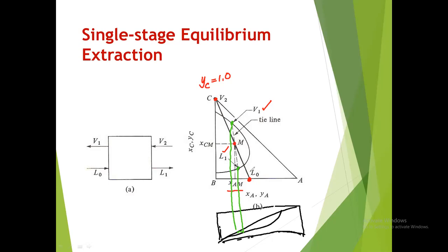On this particular line connected by these two points, you have the bulk phase M taken from the projected concentration XAM to this particular line LOV2. Then the tie line is determined by trial and error, as long as the points that you place in the phase envelope, referring to L1 and V1, when connected, pass through the bulk phase M.